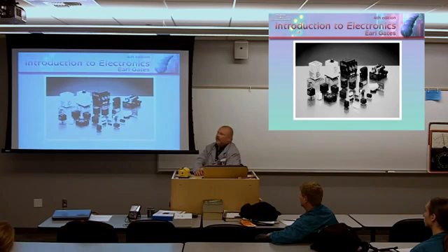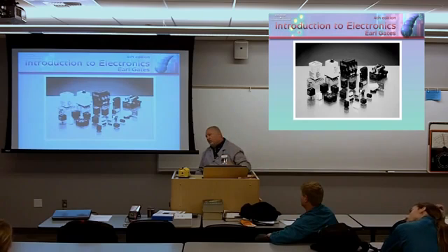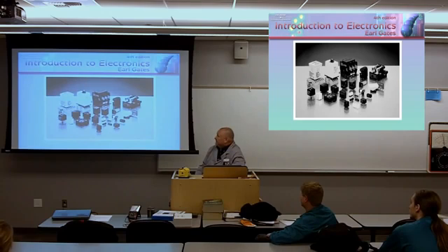Here are some examples of relays. Some of these relays are actually encapsulated so they could be put in an explosive environment, because when you open and close that contact, what are you doing? There could be a spark. So if you're working at an oil refinery, you probably don't want that spark. You want that spark to be contained, so it's going to be in a sealed relay.